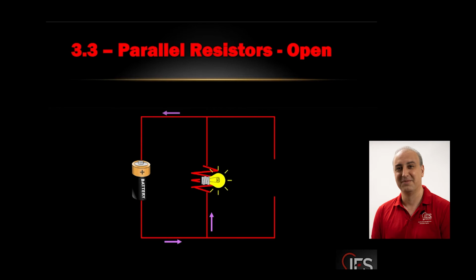I actually had an experience just a couple of weeks ago. With my Christmas lights, I have multiple branches that fall off, like a sectional, one of those icicle-looking strings all around the house. And all of a sudden, I noticed a big section of my Christmas lights had gone out. All I had to do was change one light bulb in one of the strings, and all the other ones came on. That told me that that section was on a series connection, because one light bulb going out shut down all the other ones. Now, considering that I had other parts of it that were still working, this is an example of what we call the series parallel circuit. It means you have a combination.